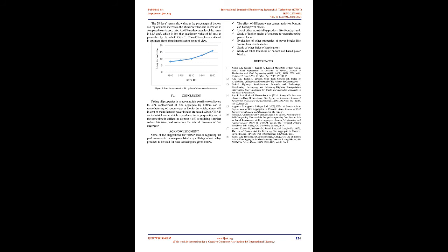The 28 days results show that as the percentage of bottom ash replacement increases, the abrasion value also increases as compared to the reference mix. At 45% replacement level the result is 12.6 cubic centimeters, which is less than the maximum value of 15 cubic centimeters as prescribed by ASTM C936-01. Thus 45% replacement level is optimum from abrasion resistance point of view.